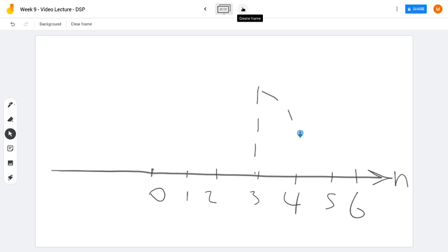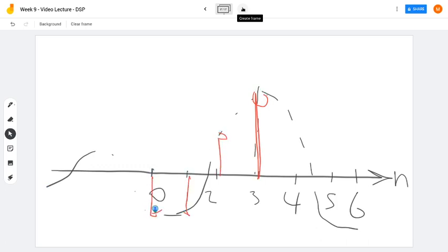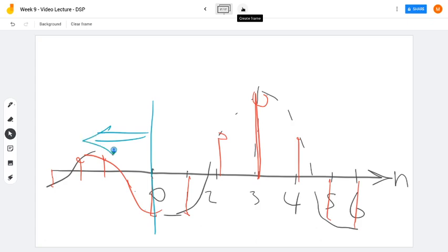So this would be our sinc function going from minus infinity to positive infinity, and the samples will be like this: sample at 3, sample at 2, sample at 1, sample at 0, and we're having samples at minus 1, minus 2, up to minus infinity, and here samples at 4, 5, 6, and so on. So this part of the impulse response from 0 up to minus infinity is causing the filter to be non-causal. That's why we will get rid of this part. We will ignore it. And we will only start taking the samples from 0.